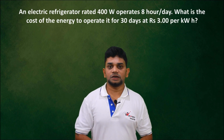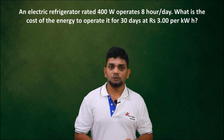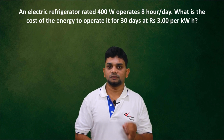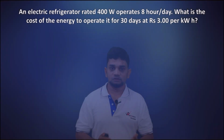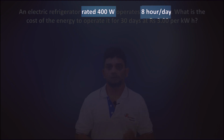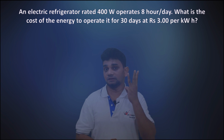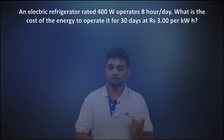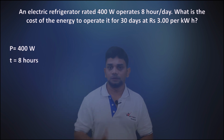An electric refrigerator rated 400 watt operates 8 hours per day. What is the cost of energy to operate it for 30 days at rupees 3 per kilowatt hour? Here there is a refrigerator. The power of the refrigerator is 400 watt and it operates 8 hours per day. We need to find the cost of the energy to operate it for 30 days, and for 1 unit 3 rupees. First we are writing the given values. Power is equal to 400 watt and time is 8 hours.